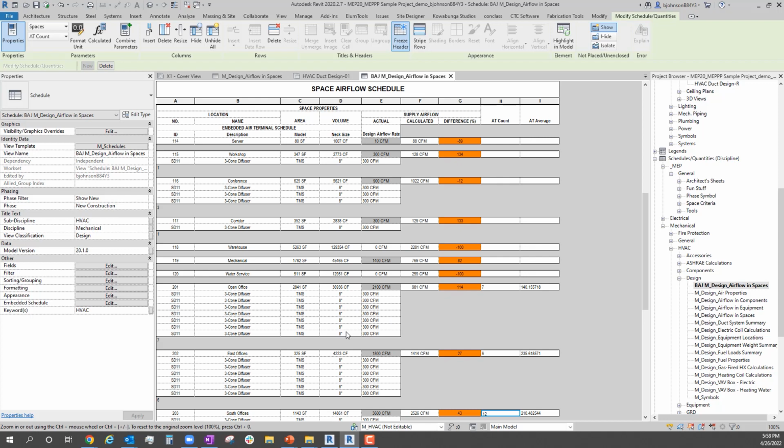They were 6-inch necks, and they're going to go up to 8-inch or 10-inch necks. If my flex duct and everything is already all connected, I may not have enough room for the fittings if I put my VAV close to the deck, and then it can't make that change. So by doing the sizing routine or drawing a size I thought was actually correct, do the 6-inch directly from the object up to my branch line or whatnot, then I can